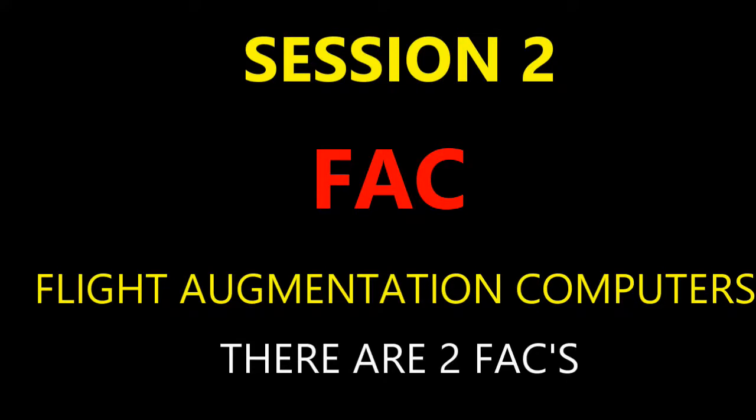Now, the time that the fault light will come on, so this is a big deal, is if you have a temporary power loss. If that happens, then the word FAULT on the push button is actually going to light up, and you're going to have a message on the ECAM for that. And also, as far as reset, because temporary means temporary, you may have a temporary power loss, but you're going to get it back. When that comes back, is it possible to reset? Yes, you can. You reset the FAC, just using the FAC button.